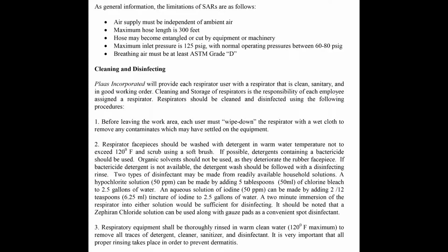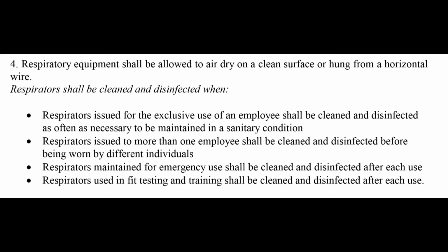It should be noted that a benzalkonium chloride solution can be used along with gauze pads as a convenient spot disinfectant. Respiratory equipment shall be thoroughly rinsed in warm water, 120 degrees maximum, to remove all traces of detergent, cleaner, sanitizer, and disinfectant. It is very important that proper rinsing take place in order to prevent dermatitis. Respiratory equipment shall be allowed to air dry on a clean surface or hung from a horizontal wire.